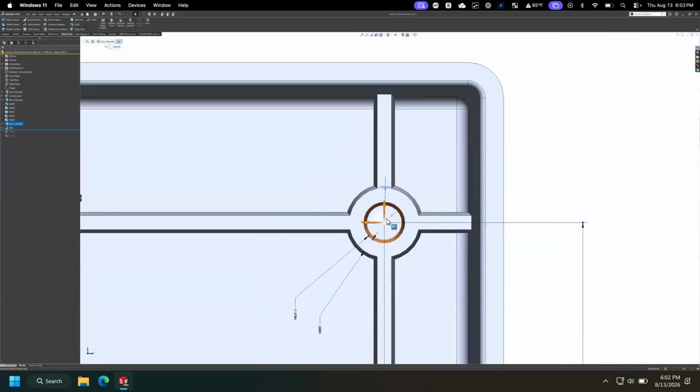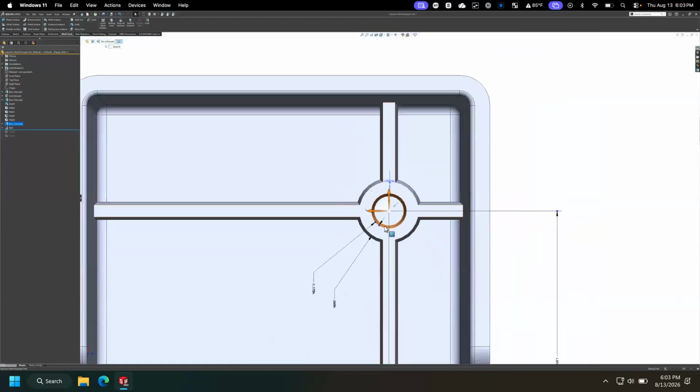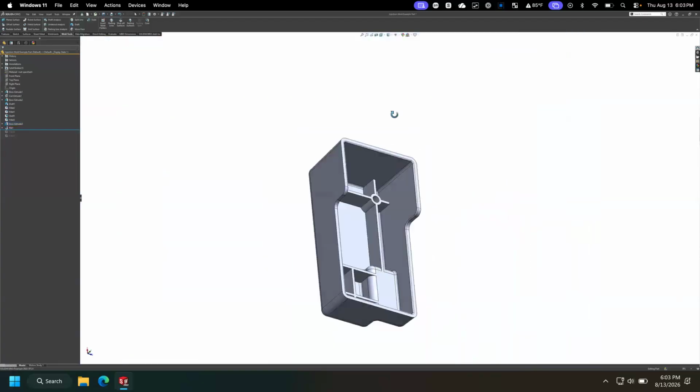Okay. But that is where you could have that, you're getting more material though. If I did want to go to a straight bore, let's say I'm using that like a screw boss and I want that to be a straight bore, well, all that extra material is now there because the draft's gone, right? And then you start getting a little bit more on the questionable side. Maybe I go to 1/3 material thickness, in that area specifically. So start playing with those features.